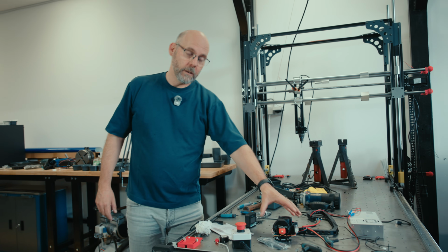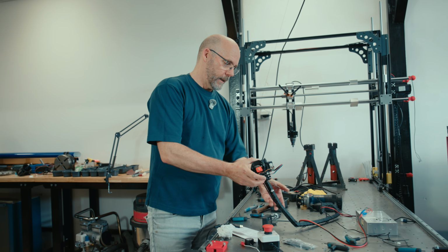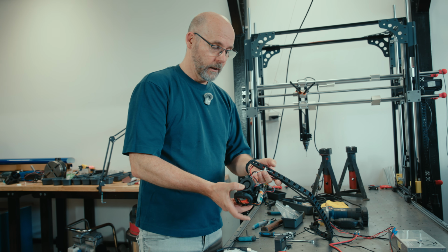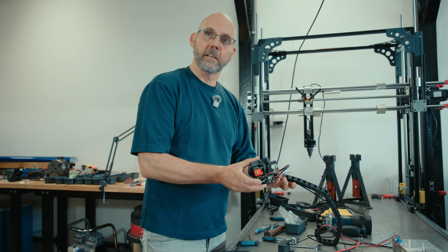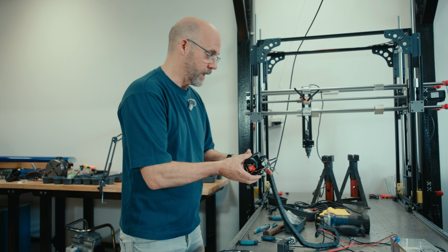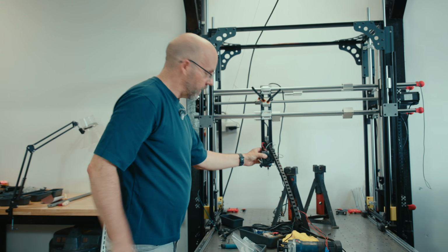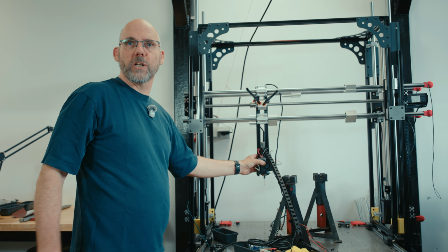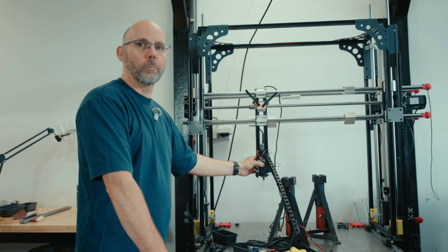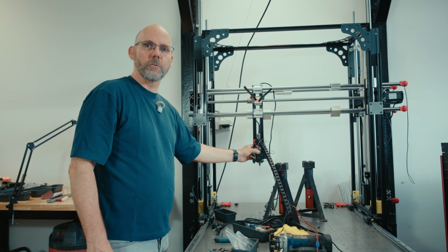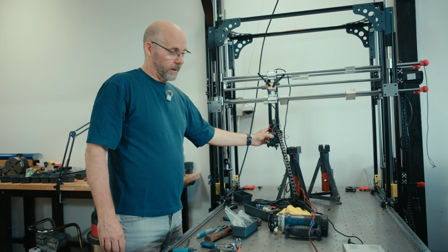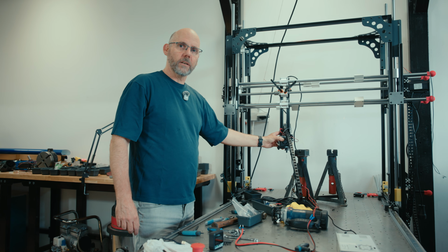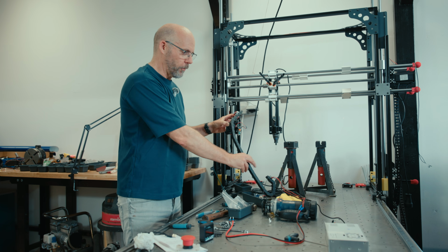So for example, what I've got here is a pretty good in-head extruder printer head. Well, we're also going to make that compatible with the machine. And at that point, we've got a huge surface area that we can print on. The table won't be heated, so we'll have some adhesion problems there. And we'll have to work on that. But we could preheat the table maybe, just with an external heater. We'll have to figure out how to make that happen.